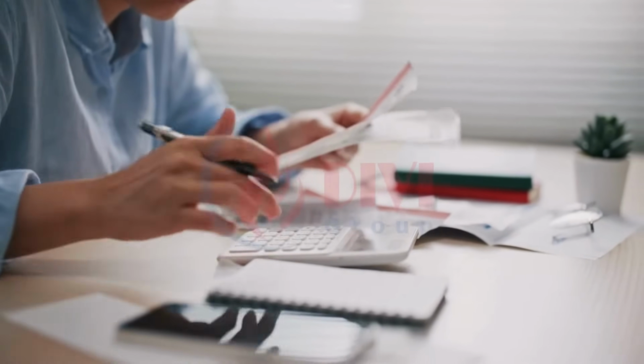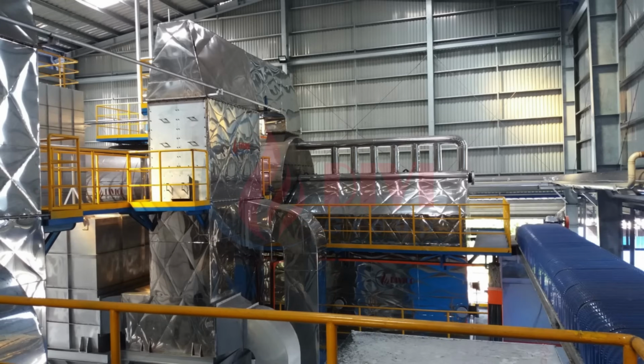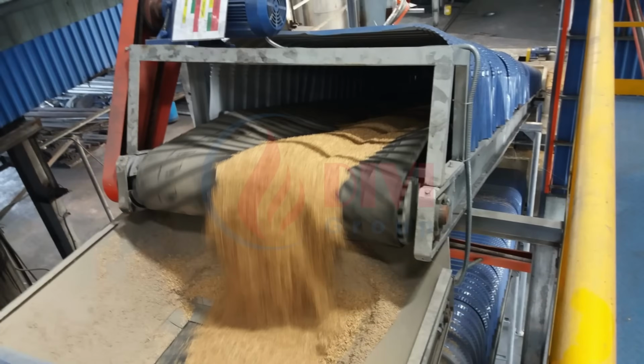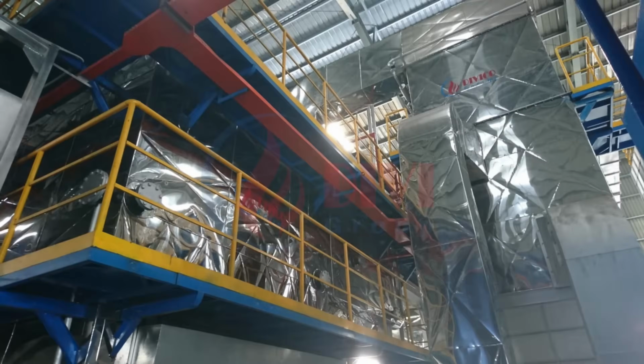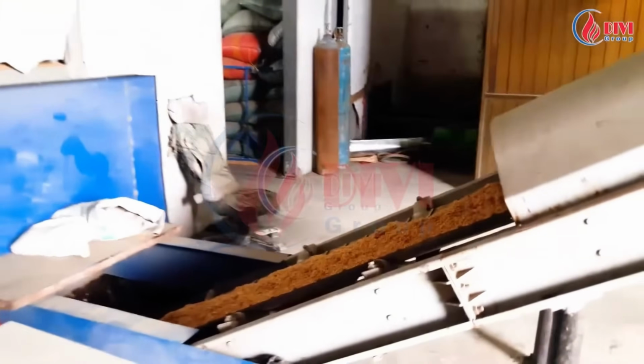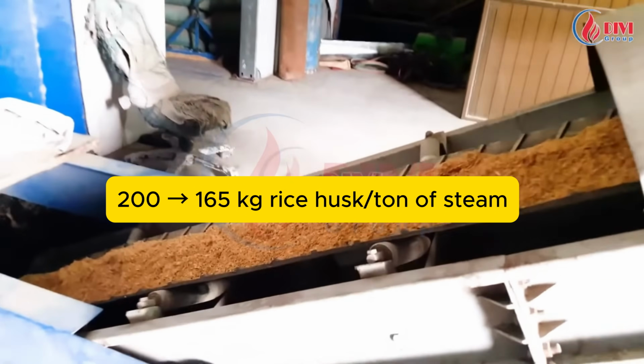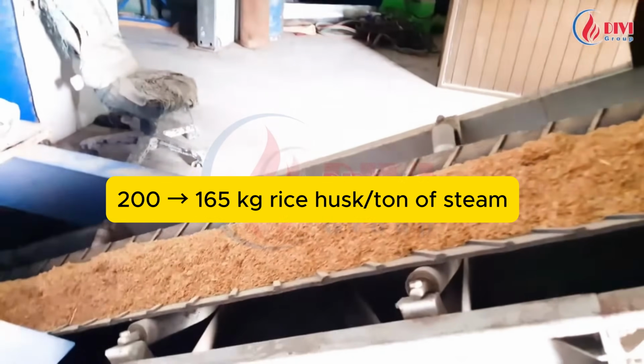For example, at Shiseico, Saomai Group Anjung, after installing the system on 2 15-ton biomass boilers, fuel consumption dropped from 200 kilograms to around 165 kilograms per ton of steam. That's a savings of about 20%. In addition, a 15-ton boiler can now operate smoothly at up to 16 tons.